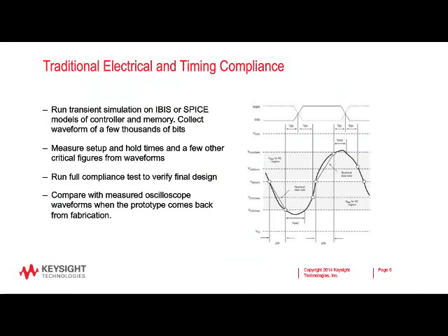So the idea of the electrical and timing compliance, before we get into the BER, as compared to the traditional method, is you run a transient simulation on IBIS models or SPICE models of the controller, the memory, and the channel. You can collect waveforms of just a few thousand bits to do the electrical and timing specs, so it's not too prohibitive in terms of simulation time. You can measure the setup and hold time and a few other critical figures from the waveforms. You can run this full compliance test to verify the final design and then compare the measured oscilloscope waveforms when the prototypes come back from fabrication.